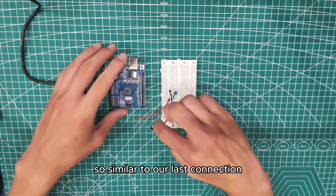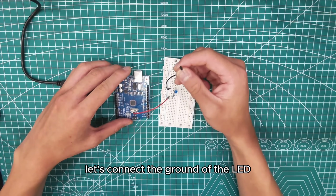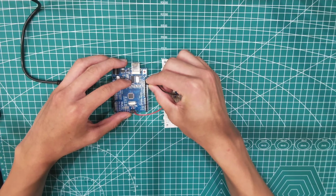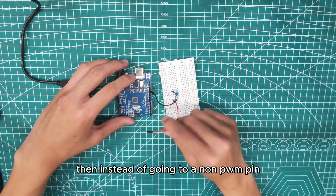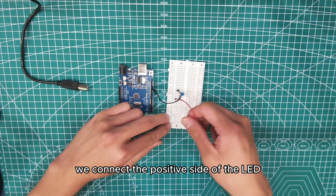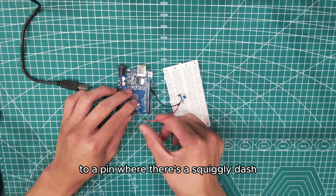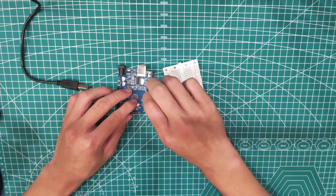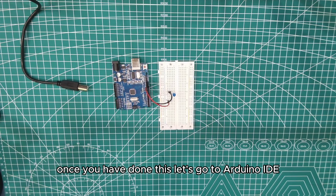So, similar to our last connection, let's connect the ground of the LED to the ground of the Arduino. Then, instead of going to a non-PWM pin, we connect the positive side of the LED to a pin where there's a squiggly dash. So right here, I'm going to work with number 11. Once you have done this, let's go to Arduino IDE.